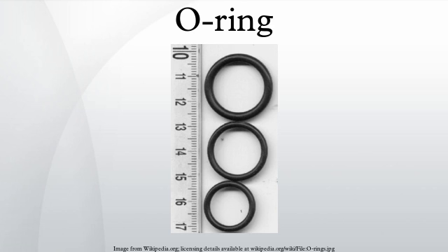Styrene butadiene rubber, thermoplastics, thermoplastic elastomer styrenics, thermoplastic polyolefin LDPE, HDPE, LLDPE, ULDPE, thermoplastic polyurethane polyether, polyester. Polyurethanes differ from classic elastomers in that they have much better mechanical properties. In particular, they have a high resistance to abrasion, wear and extrusion, a high tensile strength and excellent tear resistance.